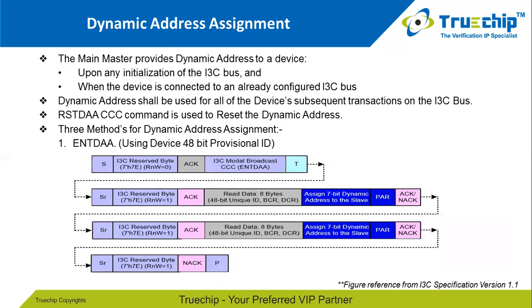For addressing, an I3C slave device supports at least one of the dynamic address assignment methods based on SETDASA, SETAASA, or ENTDAA common command code. We can also assign an address to multiple I3C slave devices on an I3C bus using the group address assignment procedure.